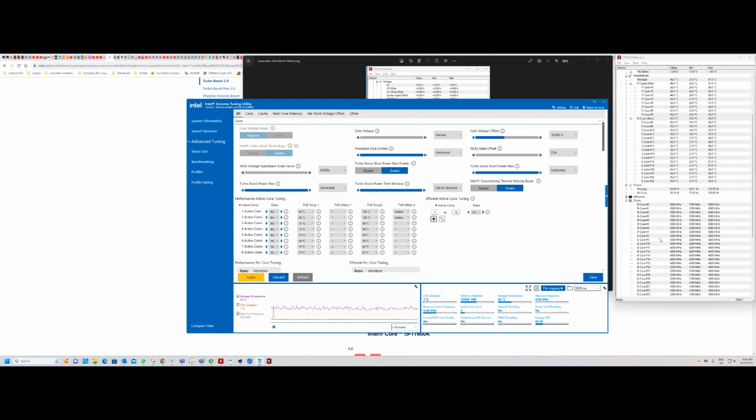This actually can be very useful, especially to help manage your temperature as well as the amount of voltage used. It can be very helpful, especially to keep stability. After I switched the overclocking terminal velocity boost on, I found that I wasn't experiencing any more thermal throttling and no power limited throttling as well. This allowed me to understand that I did reach a good amount on the offset, which is again negative 0.080 volts, with stability and overclocking as well.